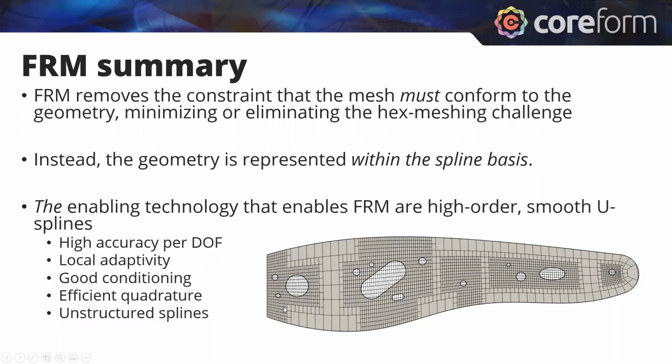So in this example, again similar to the jelly bean we showed previously, we were able to get a high quality mesh by having a single extraordinary point, which is a bit hard to see now that we've done this hierarchical refinement. But it's that unstructured nature which allows us to build this partially body fit mesh, where we've immersed just the interior features on this shell.